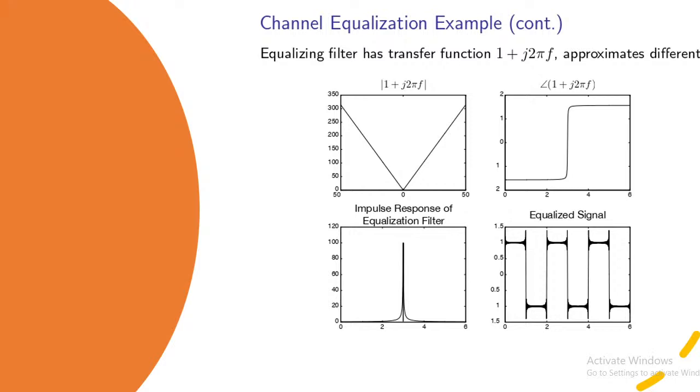So it is almost the same as the square wave, not exactly, because at the edge you can see some peaks or ringing that remains because of the Fourier transform. That will be there, but we can always handle that with other circuits. So you get almost a square wave as the equalized signal. You gave a square wave as input signal, and the equalized signal is also a square wave. Next.